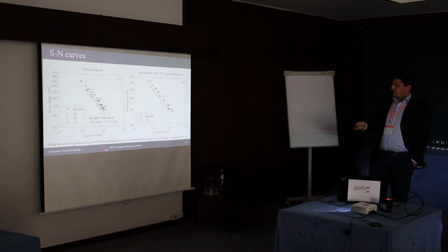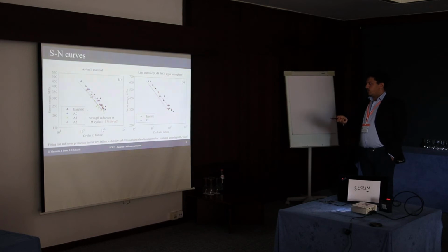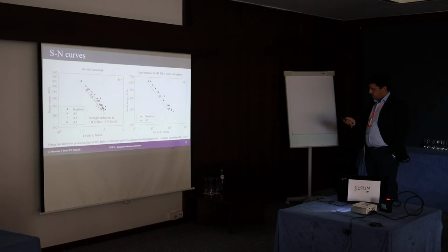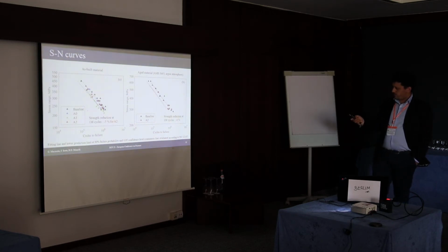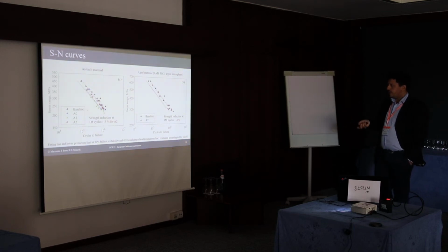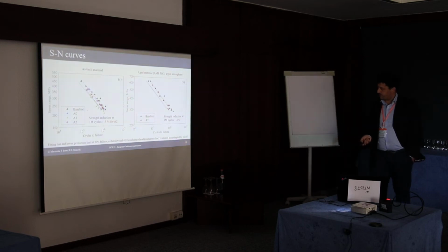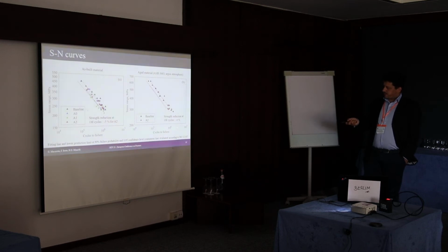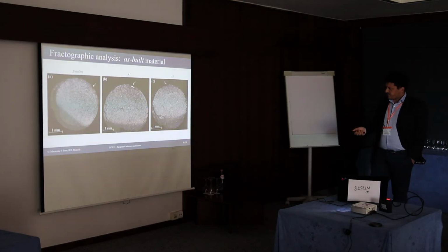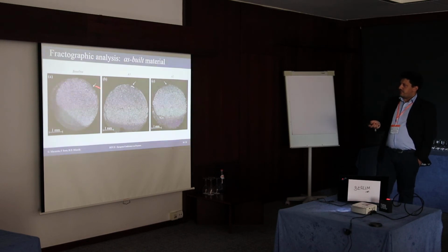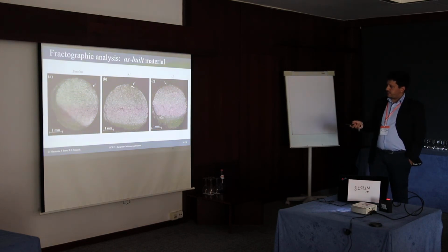And then, due to these results, we decided to age only the baseline and the ATU process parameters, that are the most promising ones. And we see that also in the aged condition, where we expected a strong reduction in fatigue strength due to the increase in the ultimate strength of the material and its notch sensitivity, we can see that the fatigue strength reduction is only 4%. It's really low.